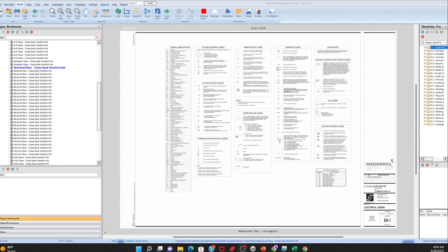First of all, to review a set of plans, and then to review the estimate and go over each part of it, and also to help you understand that when it comes to pricing, there's a standardized way, based on construction standards, of knowing how long something is going to take you to do for any scope of work in construction. How long it should take you to run a linear foot of conduit, how long it should take you to install a switch, how long it takes for a 42 position panel to be installed, how long it takes you to install a breaker.